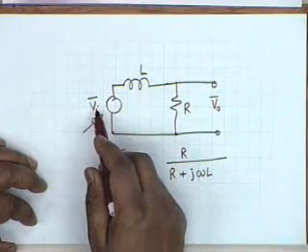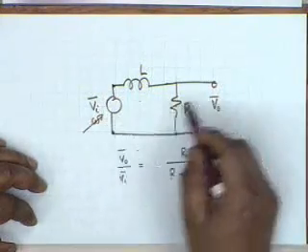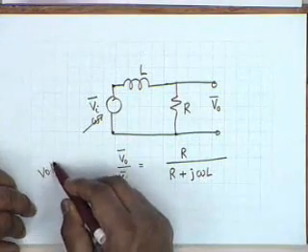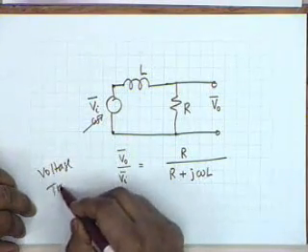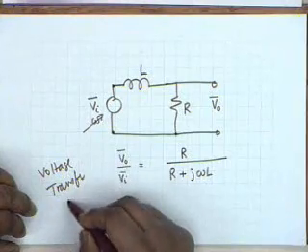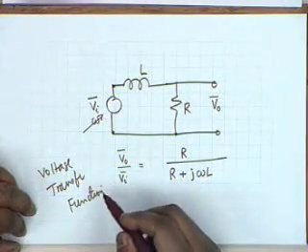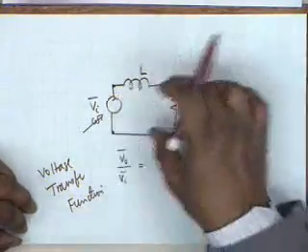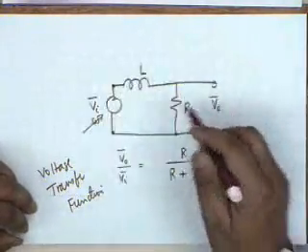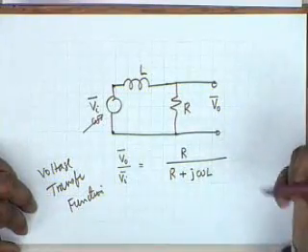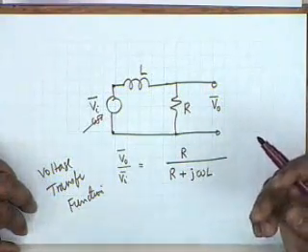The voltage is being transferred from this terminal to these two terminals. Alright, so it is the voltage transfer function. Is this term clear? Voltage is being transferred from one point to another. And what we want to do at the output is retain certain frequencies and reject others.